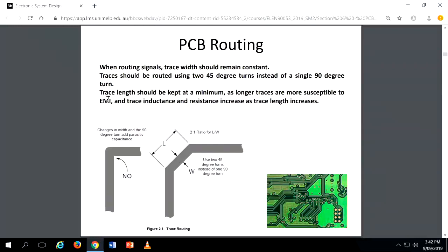So what will happen when the charge is oscillating? It's kind of a dipole antenna, so that variation can couple. It can emit or it can couple to the next one due to inductance. You may have another track going nearby, then if this track is varying quickly, it can couple to the other track. So electromagnetic interference. Also, if the length is more, as I said, at high frequencies you have parasitic inductance, parasitic resistance. These are the monsters you will be seeing at very high frequencies.